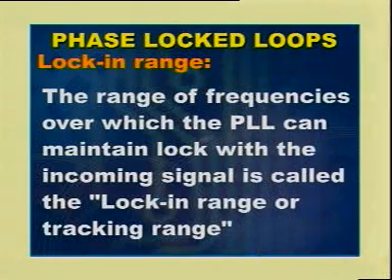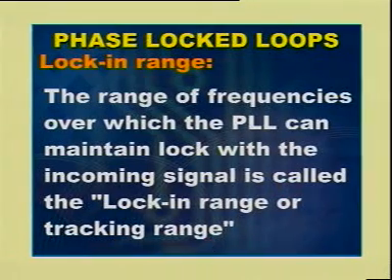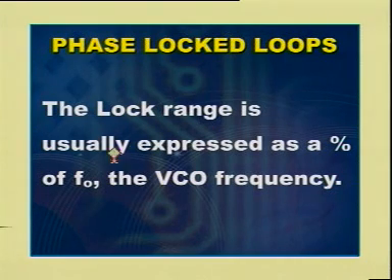Now, let us consider important definitions related to PLL. They are: 1. Lock-in range. The range of frequencies over which the PLL can maintain lock with the incoming signal is called the lock-in range or tracking range. The lock range is usually expressed as percentage of F0, the VCO frequency.